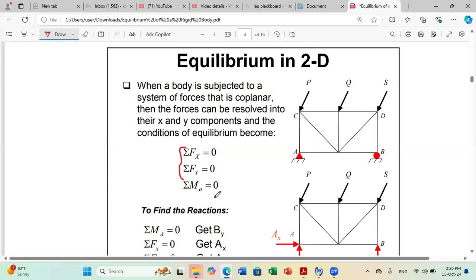But also, I have the freedom to replace a force equation by a moment equation. What do I mean with this? I can say, to have equilibrium, sum of moment about A should be 0. So I can write a first condition that sum of moment about A should be 0. I can also say that to have equilibrium, sum of moments about B also should be 0. So the second equation can be sum of moments about B